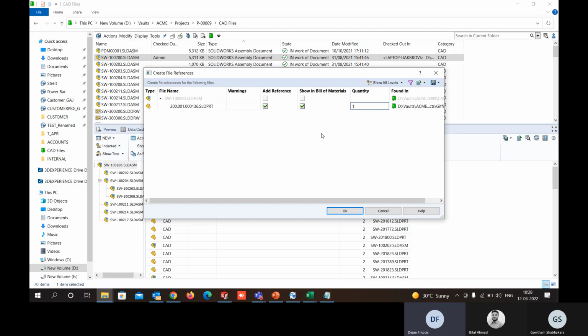You're picking sections, but those sections have their own names, and those names do not necessarily correspond to the entities that we have, and they don't have the same names and numbers as the ERP entities. So if somebody is trying to do a structure and is using weldments to do it faster, when we build a BOM, that BOM doesn't have any correlation with the ERP.